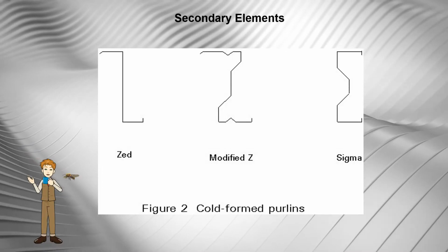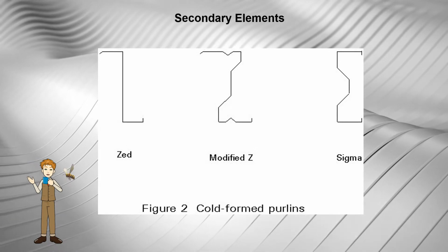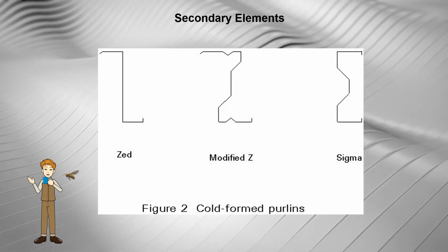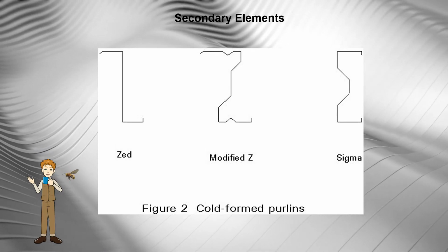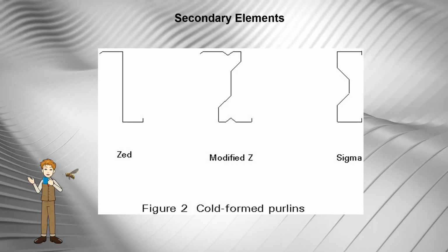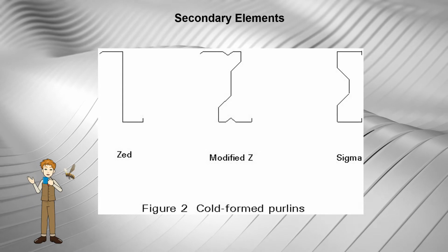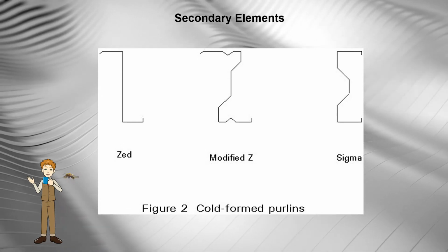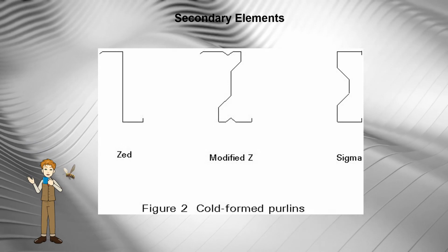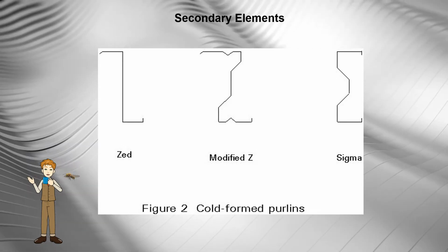In the normal single-story building, the cladding is supported on secondary members, which transmit the loads back to the main structural steel frames. An economic solution is provided by the use of cold formed light gauge sections.